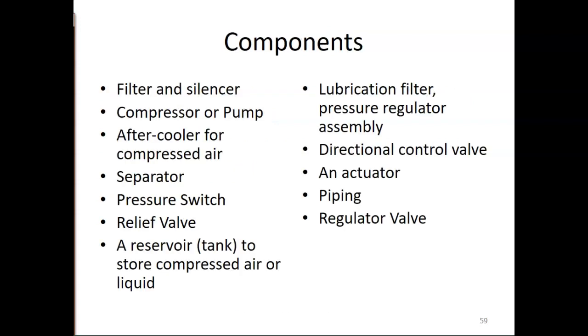So with components, you have to have a filter or silencer on a lot of air. We have silencers, or they can also be called a what? What's on your vehicle that muffles the noise? It's a muffler. There's several names for this particular part. Filters. You have to have filters constantly on a lot of these. Why? Because if it's air, we don't want pollen, the evil yellow death cloud that comes about this time of year, to mess up the internals of any of our systems.